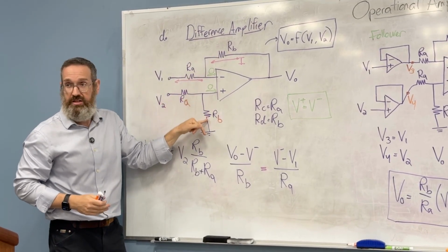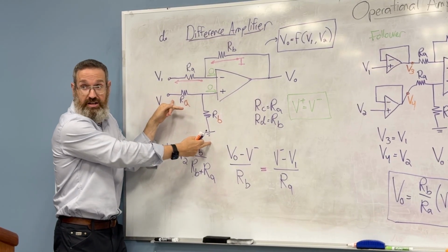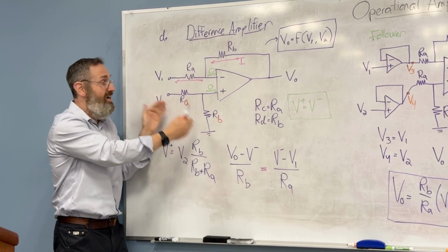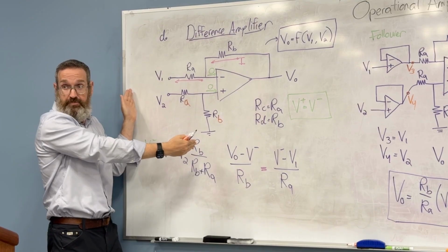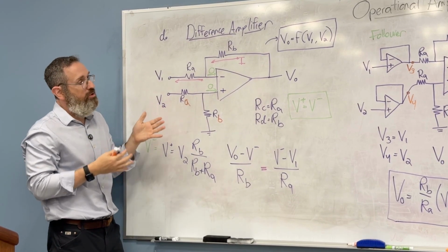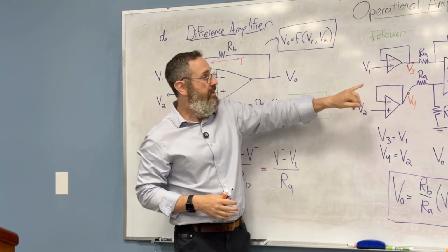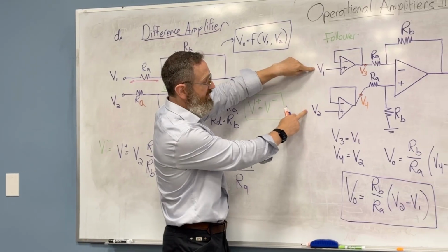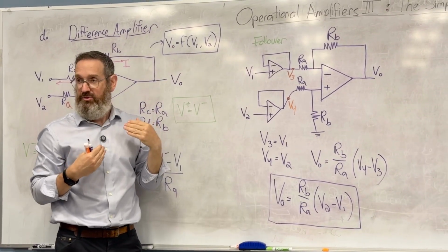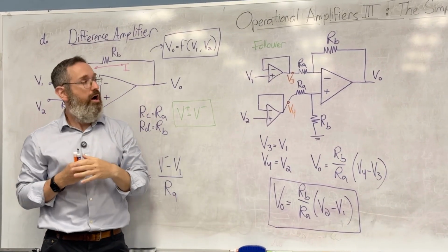And this current is not 0. So if you can imagine there's a voltage divider here and then another voltage divider, we went through that example where it's not two voltage dividers anymore, is it? It's some other circuit, right? And so it's not that it's not manageable, but I would like to live in a world where I can just take a difference amplifier and I can just drop these points in, measure the voltage, and not interfere with anything that came before. So that is at the high level.